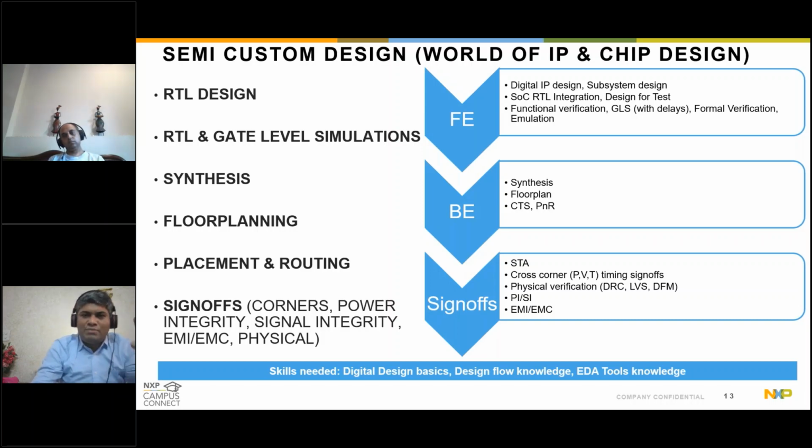When you talk of front end and back end in the process world, it is about the front end of line and back end of line, how the chip is getting manufactured in the foundry, where back end of line is essentially the metallization steps. Front end of line is more the foundation layers, the active layers, the polygates and stuff like that, which is closer to the semiconductor fabrication area.